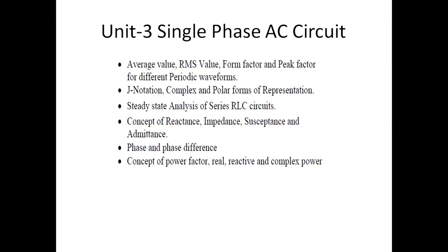After this, you have to have some idea about the reactance, impedance, susceptance and admittance. These are the terms related to impedance. Suppose you have series connected RLC networks. If you are asked to find the value of the impedance, it will simply be the phasor division of the voltage and the current. Suppose you have the phasor voltage V and the current through these elements, if they are connected in series, is I, then the phasor division of V and I will give you the impedance. That is the concept of impedance.